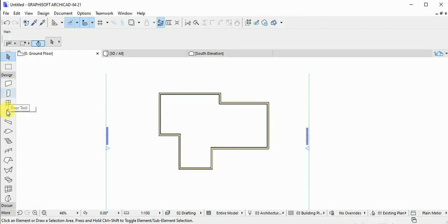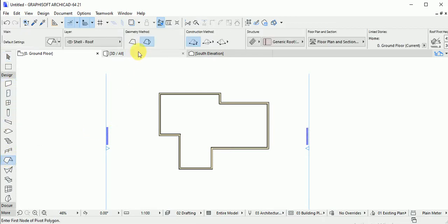Assume I want to draw a roof on it. I click on this. Remember, these are the basic settings. This side is your flat roof, while this side is your hip roof or gable roof. It depends on which one you want to make use of. Once you make use of this, let me, for instance, use single. But I don't want to use single form. I want to make it on box. You see, now it's box.